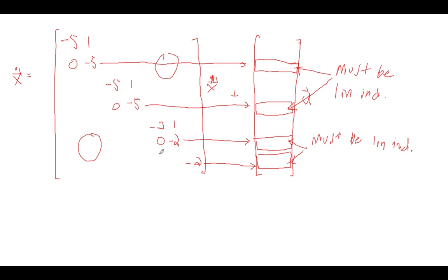You make sure for all the Jordan blocks, including if there were only one Jordan block, those rows are linearly independent. In the case of only one Jordan block, what it would mean to say this row has to be linearly independent when it's the only row is it just has to be a non-zero row. So this has all been about controllability, but the interesting thing here is we haven't actually done any numerical test. We've just looked at the Jordan form and we can see if it is or isn't controllable.